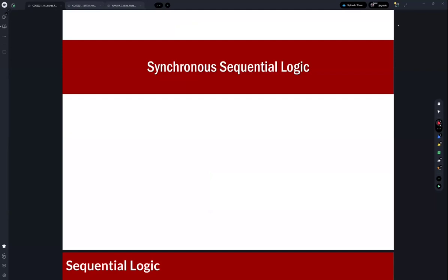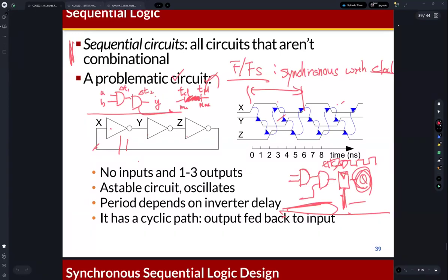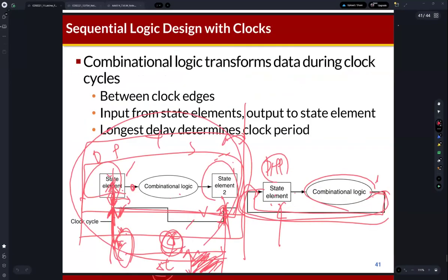If we use D flip-flops, the signals are just updated right after the rising edge of the clock, right? So actually on the rising edge of the clock, but we can also observe some delays. That's why I said right after the rising edge of clock.